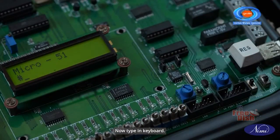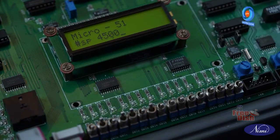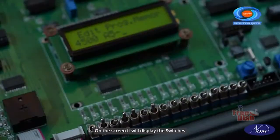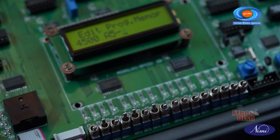Now type in keyboard SP and the address of the data pointer, that is 4500 here. Click enter. On the screen, it will display the switch's position. Here it is A5, 10100101.